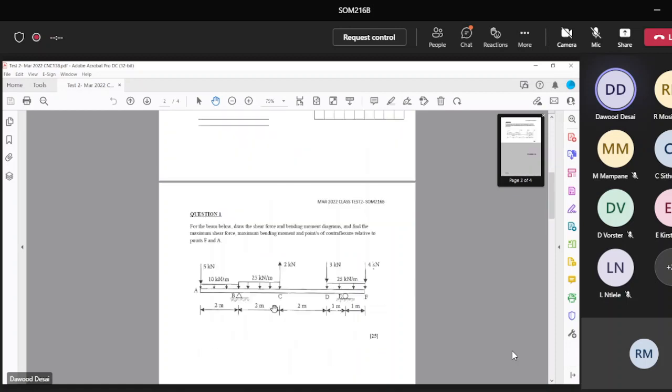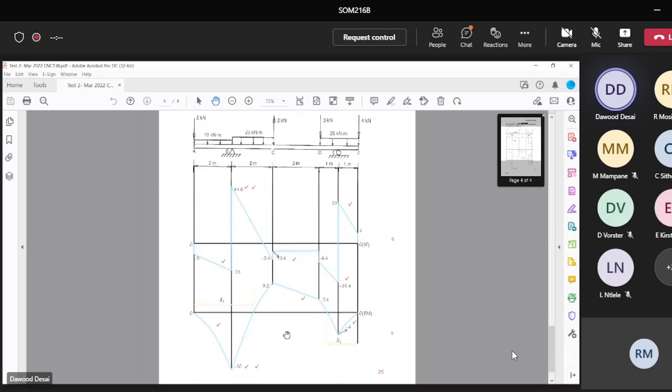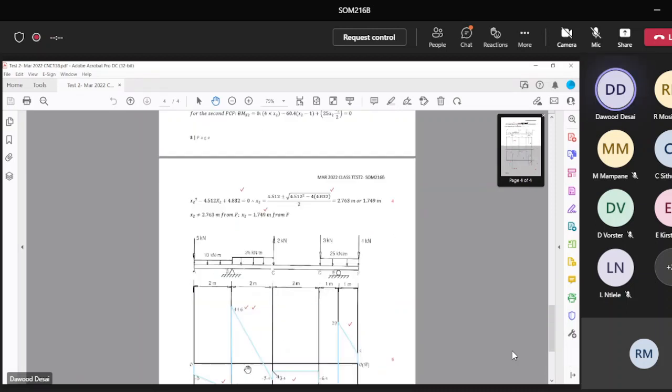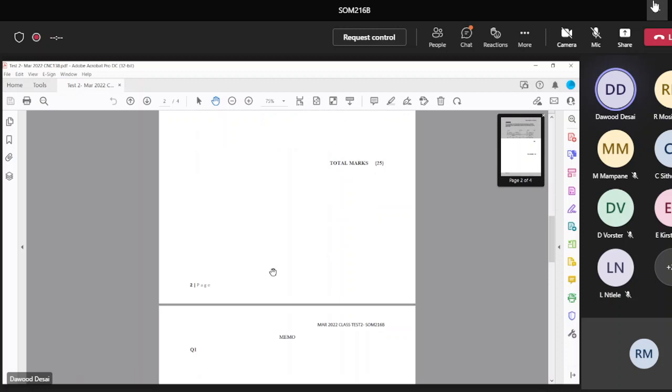Okay, the maximum shear force, you read it from the diagram, is 44. You can see the highest value. The maximum bending moment is -30. Okay, and then it wants you to find the points of contraflexure. You can just read the values off, but I always advise you do the calculation. So where are the points of contraflexure? You've got 2 points now. You've got this x1 that you want to calculate, and you've got this x2 or y2, whatever you call it. Just mathematics now, people.